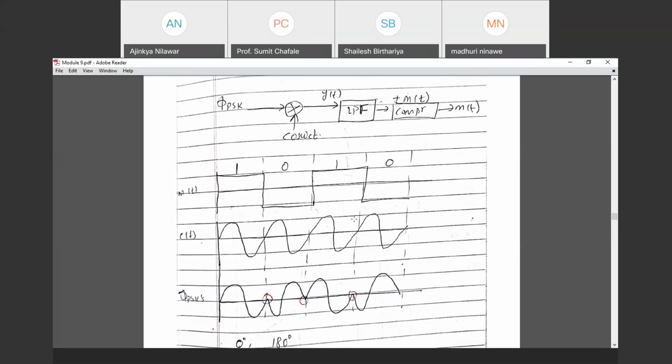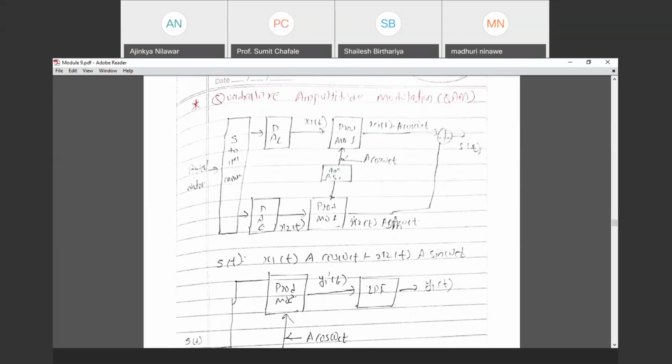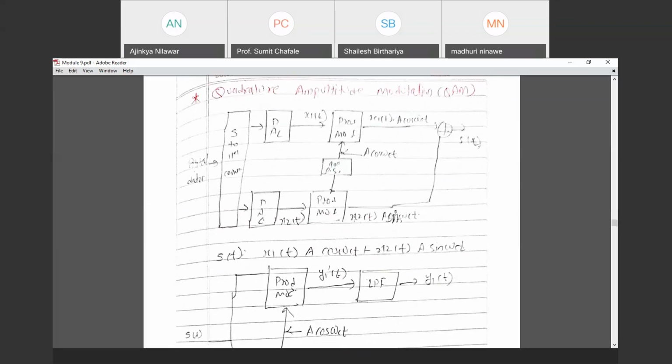Because nowadays we are using modern kind of circuitry, we always require modulation schemes, design of modulation scheme as far as communication is concerned. And nowadays we are using 4G, in which we are using the MSK technique, GMSK technique, as a modulation scheme in 4G, which belongs to the FSK. So frequency shifting technique we are using in our mobile communication, while ASK and PSK techniques combine into QAM, quadrature amplitude modulation, which is used in our TV transmission.